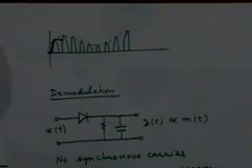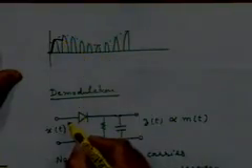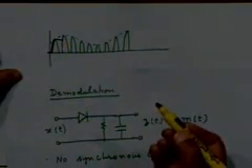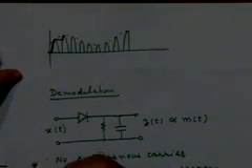Is it clear? And at this time the positive half cycle comes again. At this point the input voltage exceeds the discharged value of the voltage here, and the diode conducts again, right? And again it charges to the peak value, and that's the way things will happen.